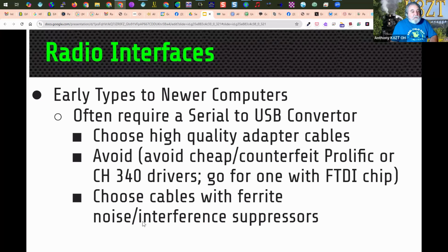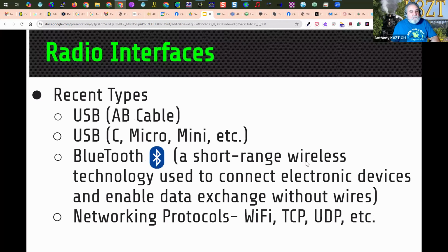Choose cables with ferrite noise suppressors, or go out and buy a nice toroid coil and wrap it around the cable, and you'll get an even better result.